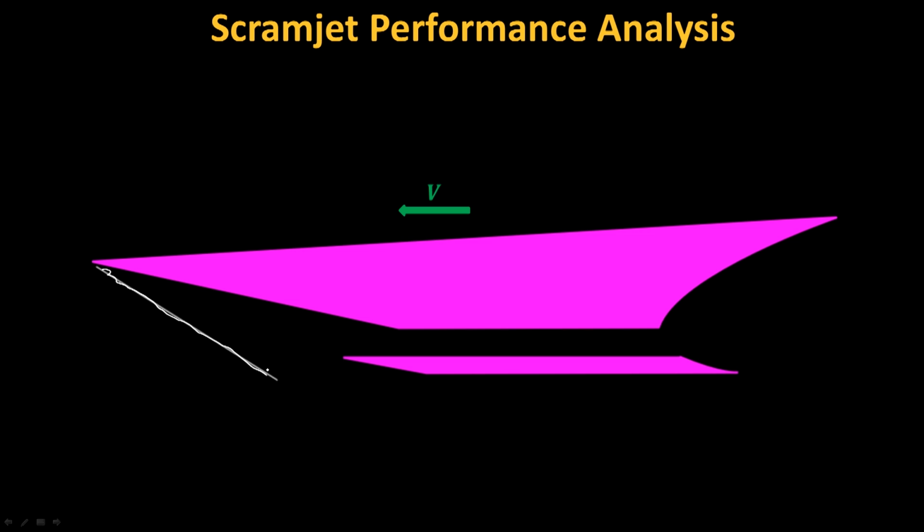Now, a scramjet-powered vehicle is made up of a couple of different parts. There's the vehicle airframe itself, there's the internal flow path, which captures the air and is part of the engine, and then there's the external cowl, which is sort of the external surfaces of the engine.